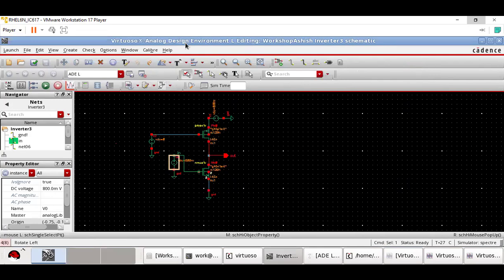Whenever I do this switching, there comes a time when both PMOS and NMOS get turned on, and the whole voltage gets downwards, the whole current flows this side. In this case, you will have the maximum voltage and maximum current. So V cross I becomes maximum.